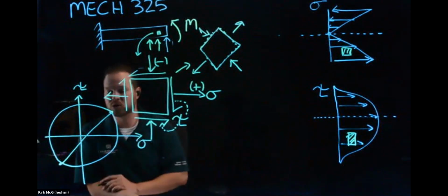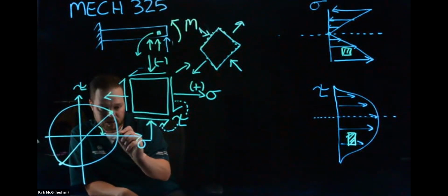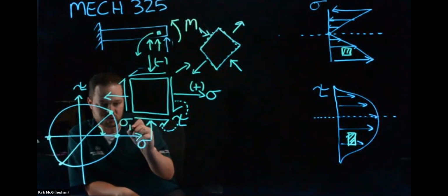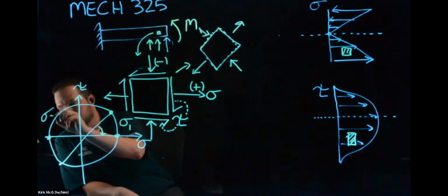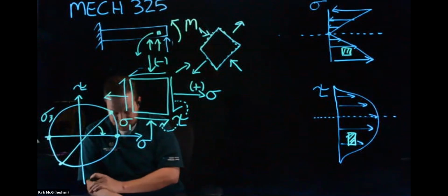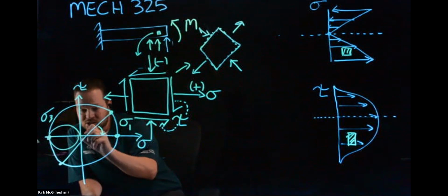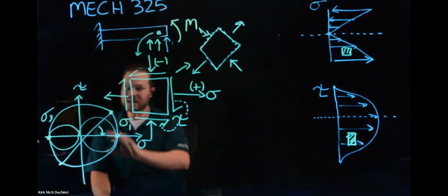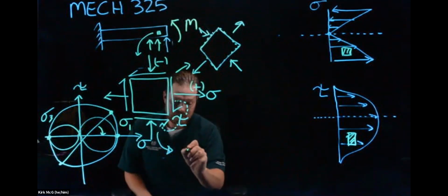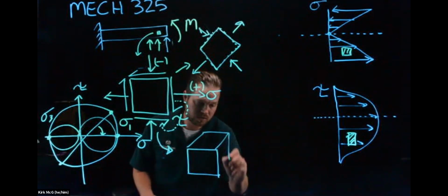The cool part about that is that's what Mohr's circle is. So if here's my component, this is my rotation. Well, now I can calculate these stresses, and these are called our principal stresses. And the cool part about this is once I understand Mohr's circle, I can also instantly move into the 3D space, meaning this 2D representation, if I use Mohr's circle correctly, tells me what's happening in a 3D structure.